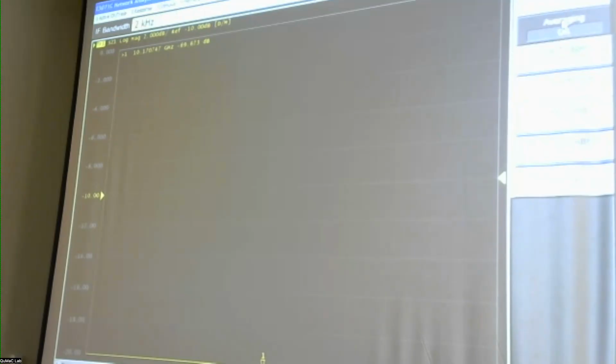Okay. So this would average 16 sweeps and display. Usually it does it incrementally, so you see that the averaging is happening. And then once it reaches 16, it will throw the first one out of the memory and add the latest one into the memory. That's a standard first in, first out kind of protocol.